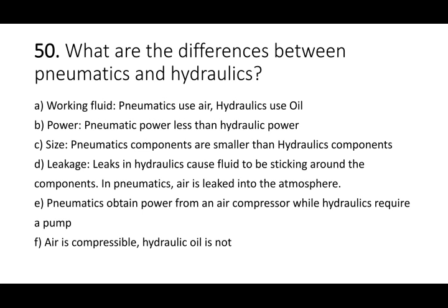Next and the last question, what are the differences between pneumatic and hydraulic? In pneumatic, air is used as a working fluid, whereas in hydraulics, oil is used as a working fluid. Then pneumatic power is less than hydraulic power. Then pneumatic components are generally smaller as compared to hydraulic components.